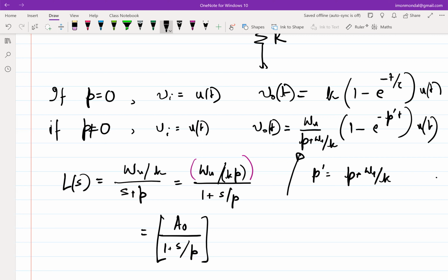So now let's try to figure out why. What is A beta much greater than 1 saying? It's essentially saying that you have sufficient loop gain, right? If you have infinite loop gain, you get whatever you want. But in Bode approximation, what we are essentially saying is that infinite is basically greater than 1, because we are doing straight line segments. So as long as things are greater than 1, there is some feedback which is coming back and correcting the error. It might not be able to correct it fully, but it's still doing some correction.